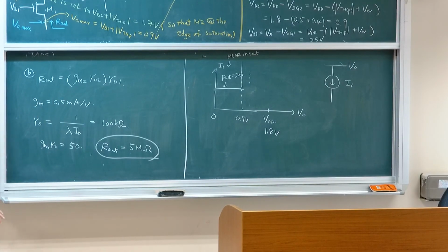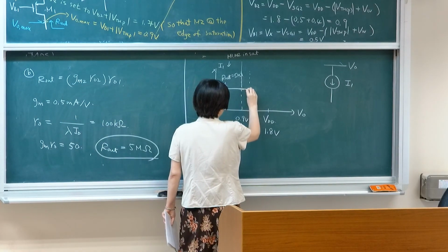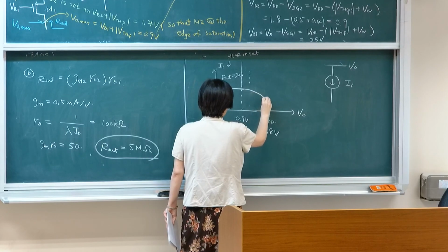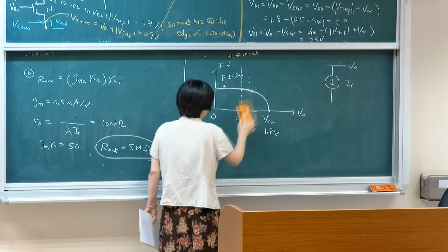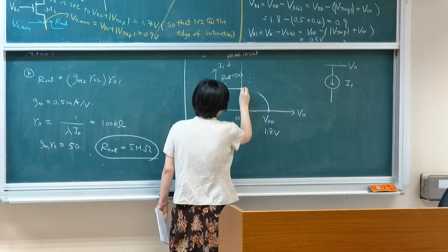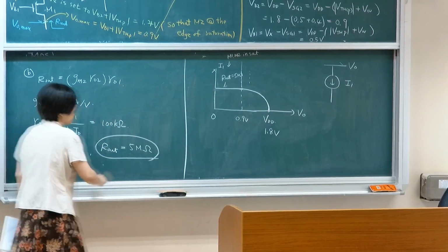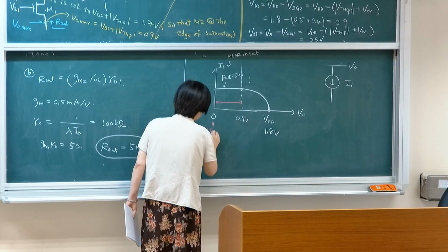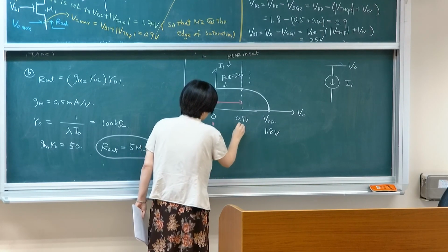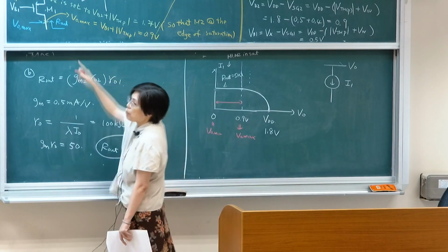When you start to enter higher voltage above 0.9 volt, then either one of the transistors will become linear, so you get degradation of its slope, and then it will go like that. So your operation region is fairly limited. This is VO minimum. This is your VO max. As I said, it's being set by VB2.